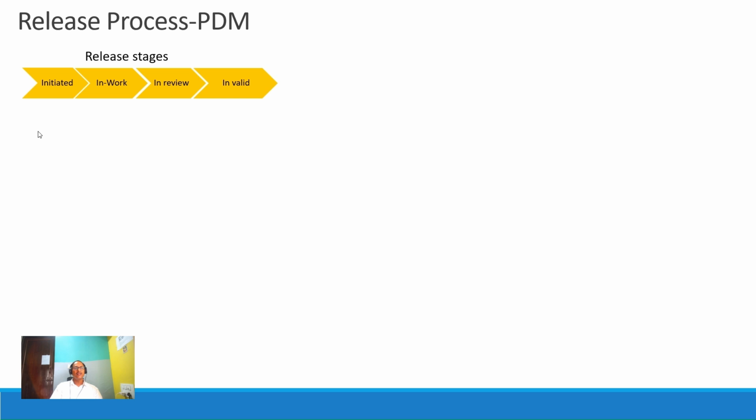Now let's see in detail what the release process is. Okay. The first step in the release process starts with the engineering change notice. The engineering change notice is a particular number or a basket where that particular set of revisions of that particular design phase is stored. Okay. So that basket is labeled with a particular number called the ECN number.